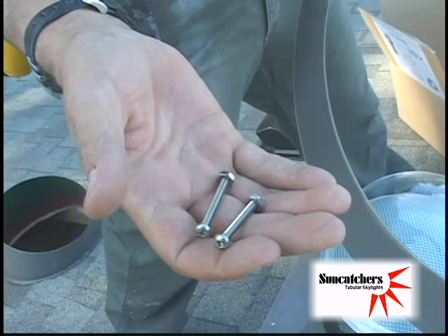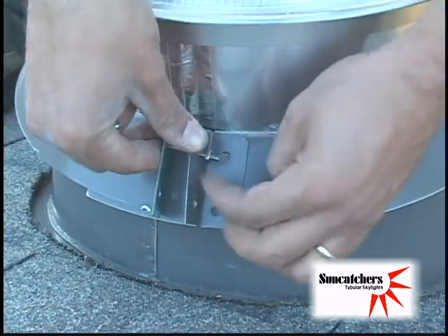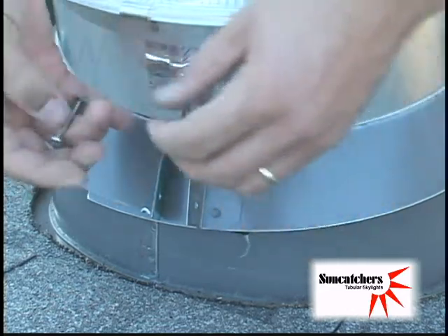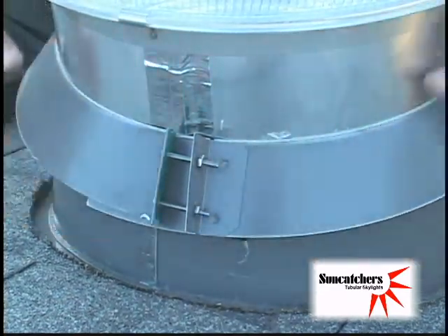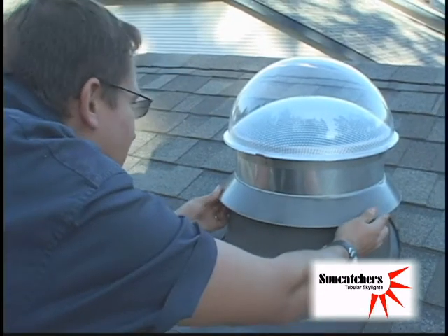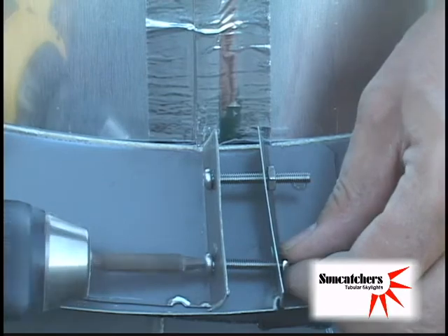Using the machine screws, fasten the storm collar above the peel and stick, finger tight. Ensure that there are no rips or tears in the exposed reflective tape on the pipe seam. Level the storm collar with the dome before tightening down for improved aesthetics.